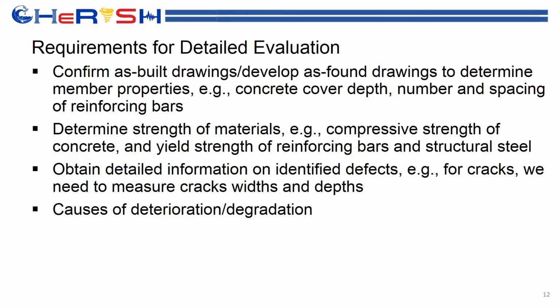And therefore, we can always resort to developing what we call as-found drawings and do some field measurements in order to determine the geometric information of the structural members, and then probably use some non-destructive tools like determining the number of rebars in reinforced concrete, the concrete cover depth, the spacing of the rebars, and so on.